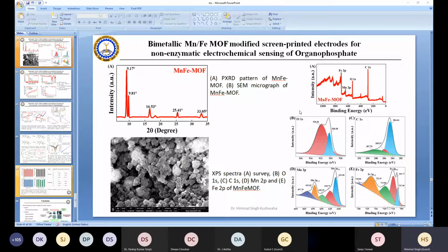It depends on what catalytic process you are using for wastewater treatment. Wastewater treatment can also be performed by the absorption process, and for this, hydrogels with embedded nanomaterials can be a good candidate. If you are using a photocatalytic process, then it will depend on the band gap, the charge transfer, the electron-hole recombination, and the absorbability of the material. So it depends on which process you are using for wastewater treatment.